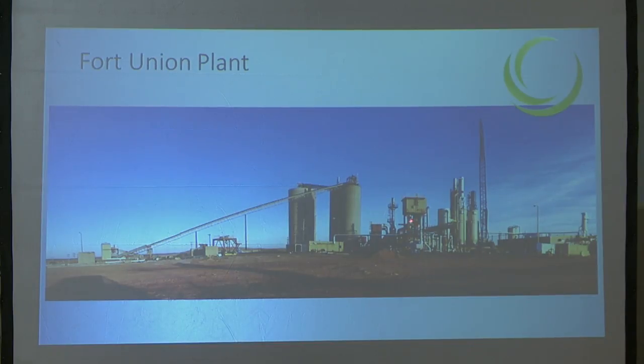So we have concurrent flow of gases and carbon come into a product collector where the carbon is separated from the process gases. The process gases are taken to an oxidizer, which is hidden back here behind this infrastructure. All those volatiles are heated up and driven to carbon monoxide, NOx, SO2, which is then emitted from the stack under our WDEQ permit. This is our only emissions point right here. Very clean. We don't have any particulates. All the particulates are captured right here in our product collector because our particulates are carbon. We don't have any particulate emissions.